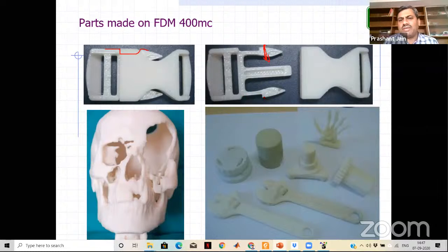And because in the FDM process, when we fabricate these parts, depending on the vector length, material, particle strength, particle size, thermal conductivity, etc., a lot of shrinkage will come, or expansion will come. So depending on the work envelope, the part may shrink, or our part may expand. So to achieve the proper fit, we have to find suitable process parameters, right?